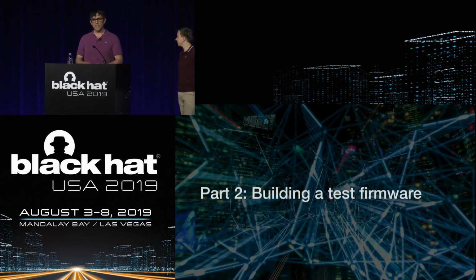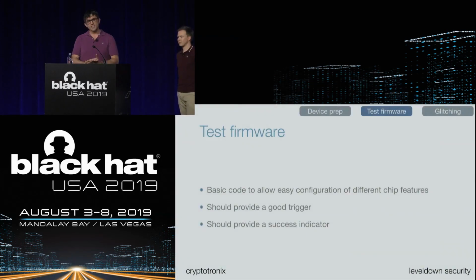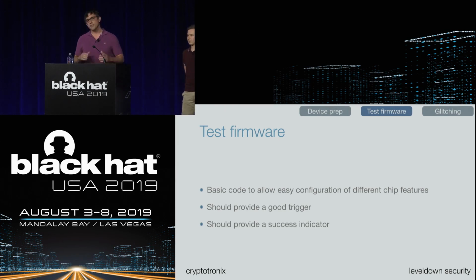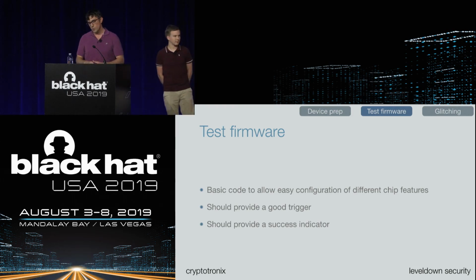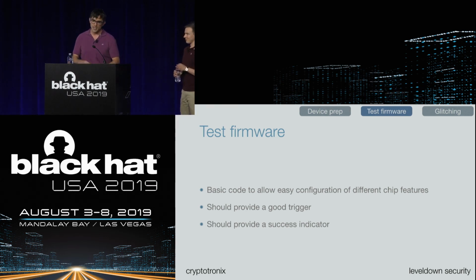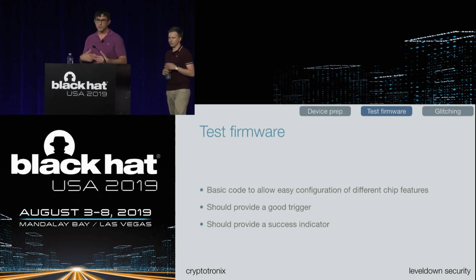Okay, so now we're going to be talking about what's the test firmware that we have to write. And this is not unlike traditional embedded development where we have to do a system bring up. So it's very dependent on the manufacturer of the chip, and this is where it's either super easy if someone else has done it and you copy the project, win, or you actually have to download the vendor's SDK and then figure out why that doesn't compile, and then fight through lots of problems of why you can't get the Blinky to work.